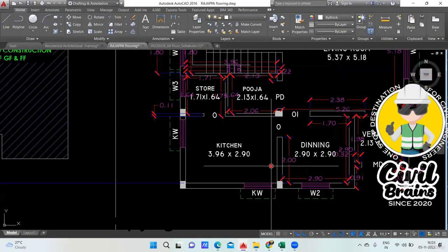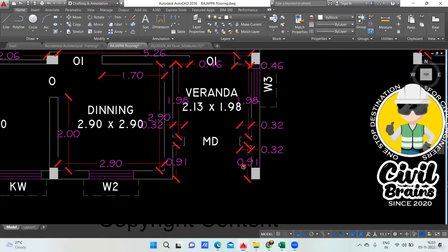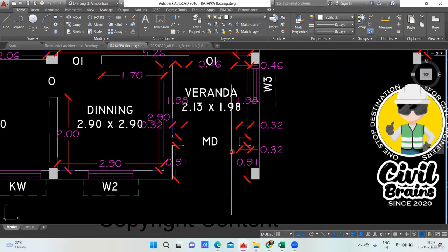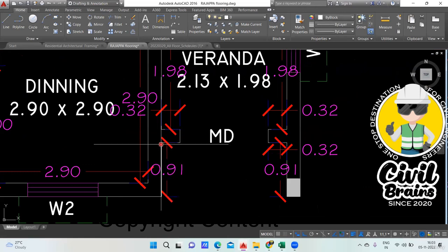For example, let us say this is a main door, isn't it? People don't want to do painting in this area. Usually people put either marble, or they make use of tiles, and for the complete wall they put these tiles. So in that case, this also comes under the wall dadoing part. You just measure the perimeter and multiply it by the height it has to go.